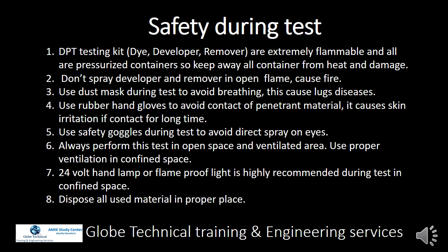Safety during test. DPT testing kit, dye, developer, remover are extremely flammable, and all are pressurized containers, so keep all containers away from heat and damage. Don't spray developer and remover near an open flame, as it can cause fire. Use a dust mask during the test to avoid breathing this, which can cause lung diseases. Use rubber hand gloves to avoid contact with penetrant material, which causes skin irritation if in contact for a long time.